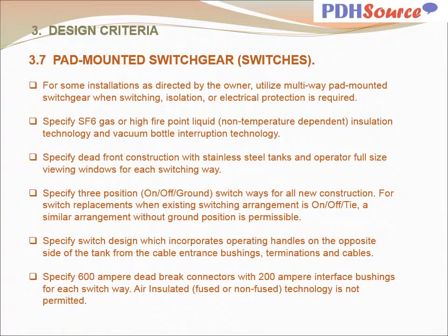Specify switch design which incorporates operating handles on the opposite side of the tank from the cable entrance bushings, terminations, and cables. Specify 600 amp dead break connectors with 200 amp interface bushings for each switch. Air insulated, fused or non-fused technology is not permitted.